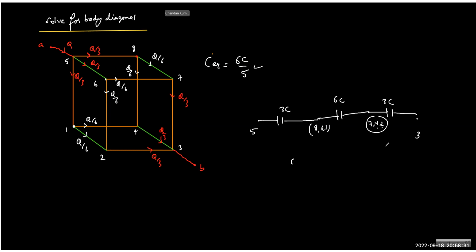No, I was getting confused with 1 actually. No, 1 is different. 4 and 2 are same, like it is flowing to 4 and 2. So you begin at 1. 1 is one of the terminals, and 4 and 2 are the other terminal. So 4 and 2 will have the same potential. Got it. And then how come 7?